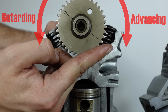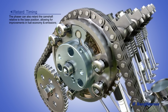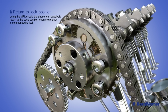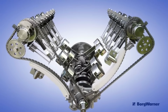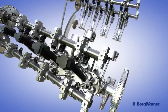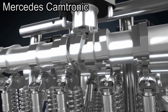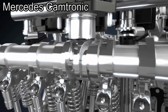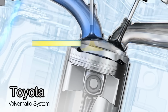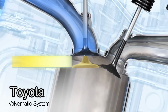And this can be done while the engine is still running. Most modern engines on cars incorporate variable valve timing systems which advance and retard camshafts as required to produce good responsiveness and torque at low RPM and good power at high RPM. Many systems even pack multiple lobe profiles into a single camshaft, and can switch between them during engine operation, giving us low valve lift at low RPM and high valve lift at high RPM, which further improves responsiveness, power, and torque throughout the rev range.